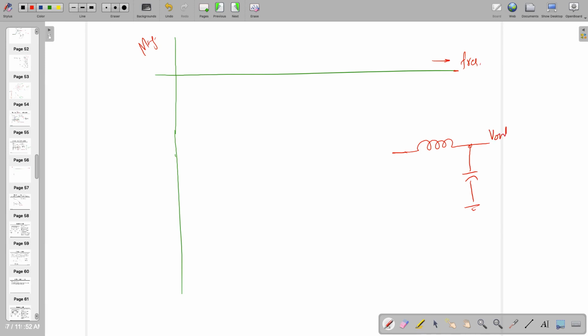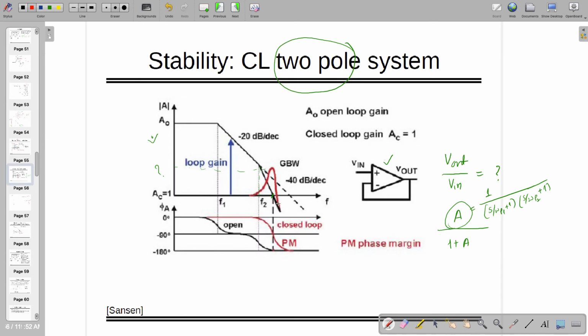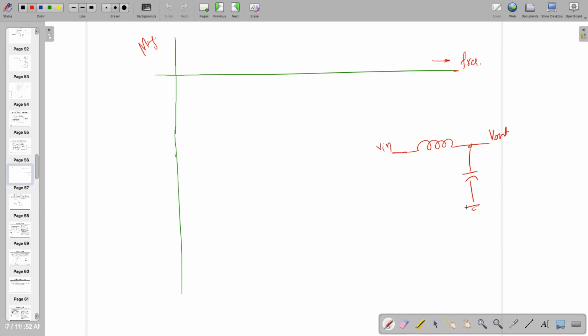Transient. So V out versus V in. Here you are saying that it's going higher, right? Similar thing, can it be possible for an RLC circuit? Yeah, but you have to tell me how it's going to happen. At resonance, the voltage applied will be completely across the resistor, so voltage across capacitor and inductor will cancel out. So we don't know the value. Maybe it can be. But can it go beyond V in?